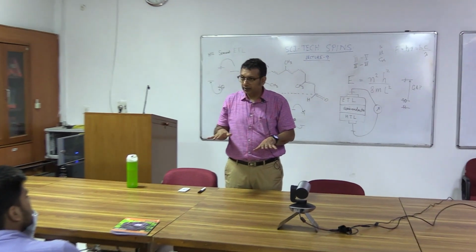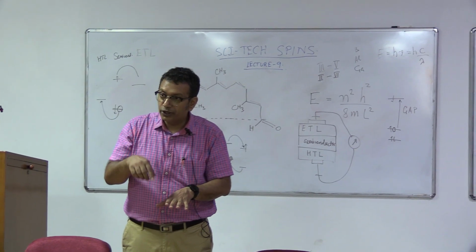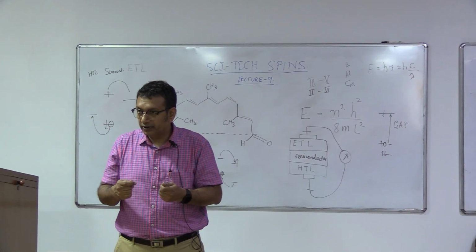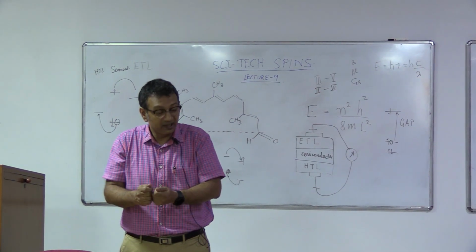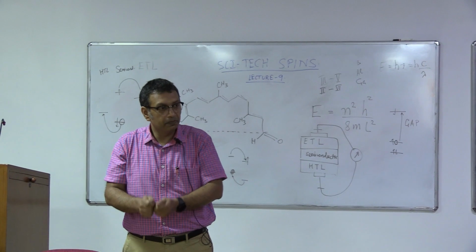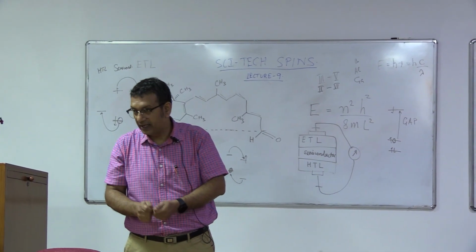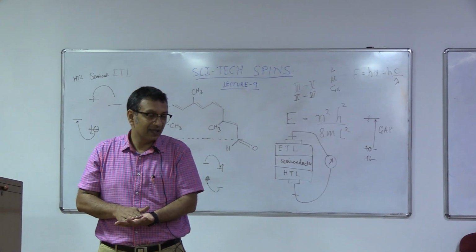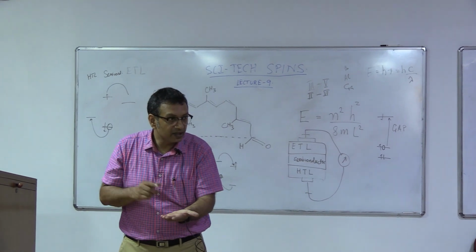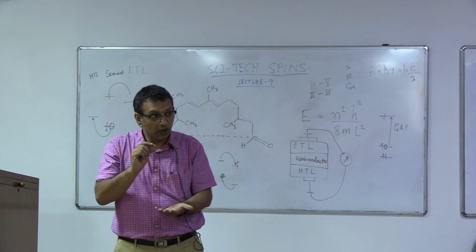But you have a substrate. On top of that substrate, you put molecules of these. So if you put gallium, arsenic, you put the precursors of these, let them react at whatever desired temperatures, they go and stick to this substrate. The substrate, of course, if it's gallium arsenide, I can throw indium gallium arsenide on top of it because that would have a very small lattice mismatch.